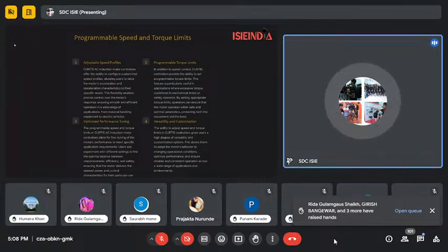And coming to the first topic, Curtis VCL, where we get programmable and adjustable speed profiles of the motor, with the help of setting the parameters through the software. Or we can say this type of controller is similar to an embedded system, with a combination of software and hardware to deliver the power and run all the power electronic components, with MOSFETs and IGBT power electronic devices for switching and efficient output.